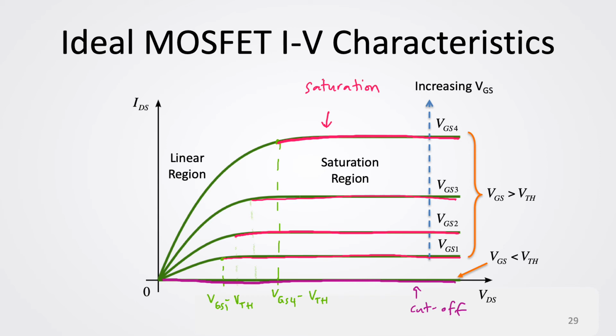So that yung saturation region natin, yung pink dito, you could see, depending on what VGS we are operating in, nag-iiba yung range of VDS kung kailan saturation yung MOSFET. So, ito yung region na saturation. So, to complete our analysis, ito yung linear region. Okay? Yun yung mga regions wherein VDS is less than VGS minus VTH.